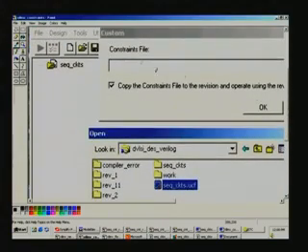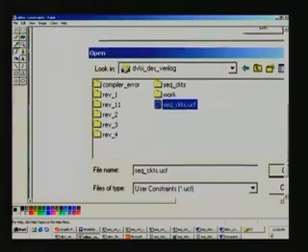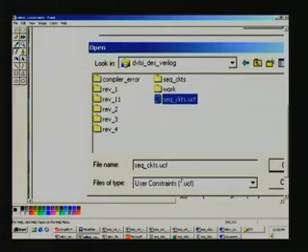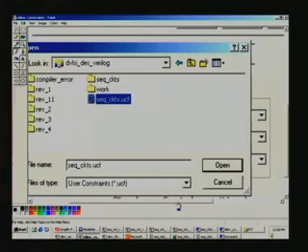This is what we have here, this constraints file, and we had just seen that another window popped up, and here you mention the file name, UCF. In fact, you do not mention it, the system will do it for you. All you have to do is use this window, go to the required folder where you have placed this UCF file, and click on that.